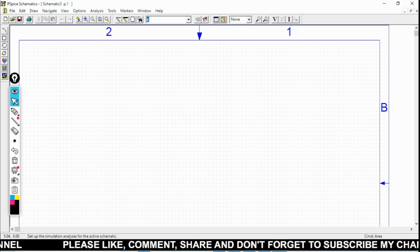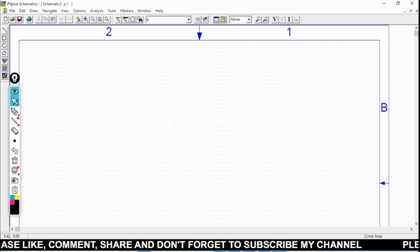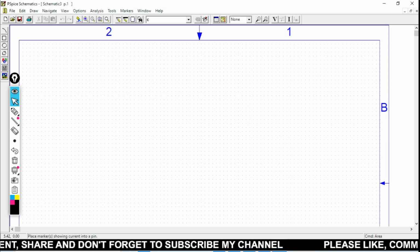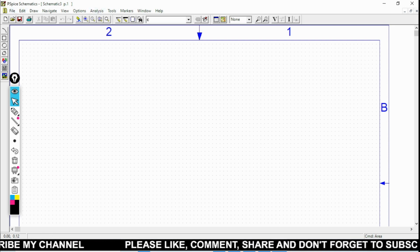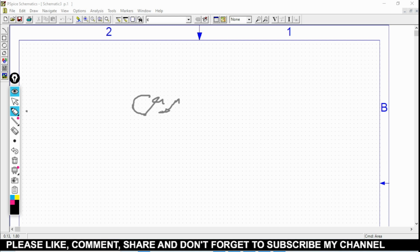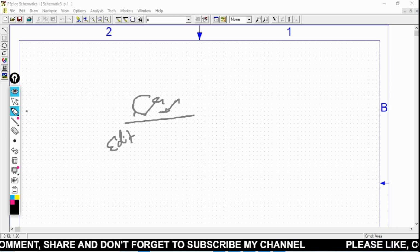Then if we want to simulate or set up, we can click here. It will go to the simulate window. This is the shortcut, and if we click on this, it will be simulated. Then these are the voltage marker, current marker, voltage levels and current levels, so you can display the voltage and current over here. This is again the extra toolbar available here. So this is the title bar, menu bar, toolbar, and this is the editor window, where you can edit.